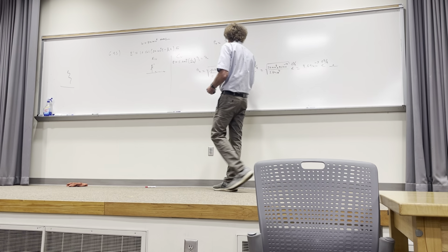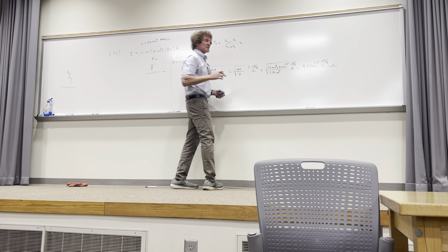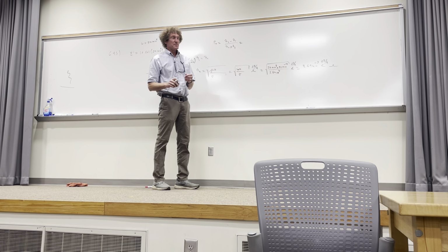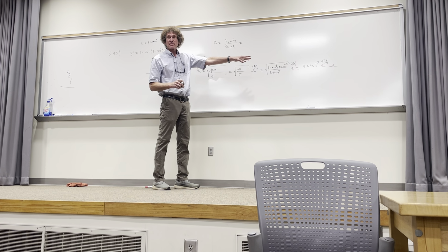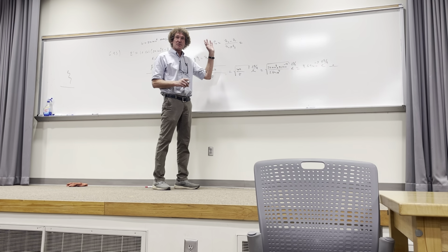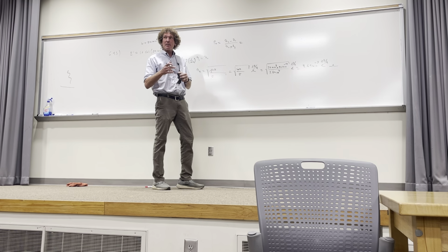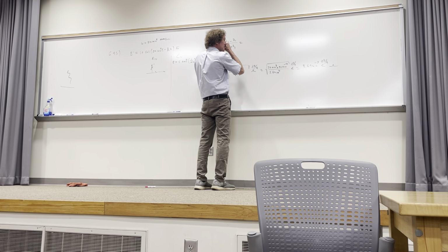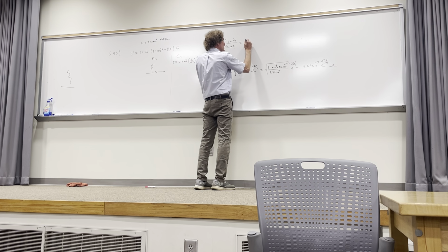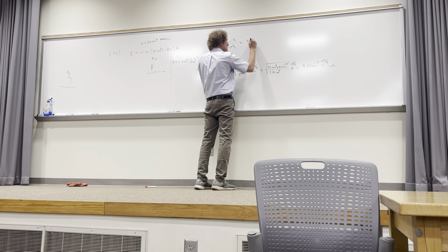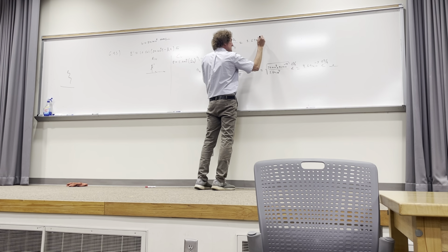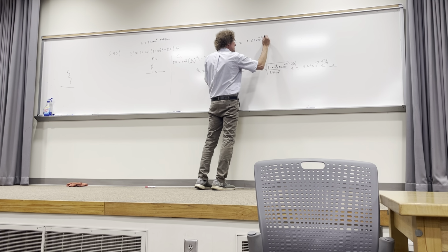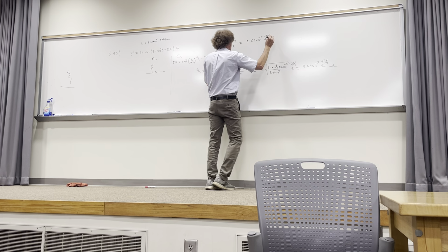Okay, now calculate this. I want you to take a look at this before you just brute force it. I've got η2 minus η1. η2 is of the order of 10 to the minus 3. η1 is 120 pi, or 377, right? You see how this really is going to be about minus 1. We can put it in there if you want to do the math on this, but we can put in the 3.69 times 10 to the minus 3rd e to the j pi over 4. It's not going to matter.